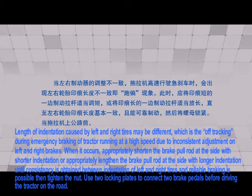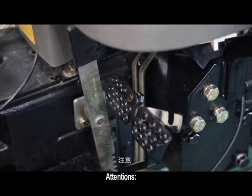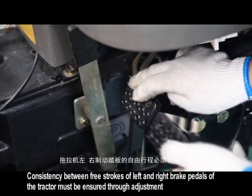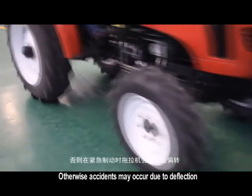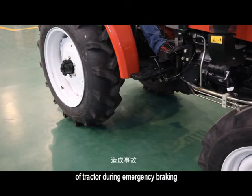Use 2 locking plates to connect 2 brake pedals before driving the tractor on the road. Attention! Consistency between free strokes of left and right brake pedals of the tractor must be ensured through adjustment. Otherwise, accidents may occur due to deflection of tractor during emergency braking.